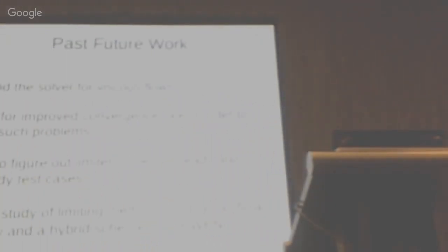So you're having an implicit solver. Yes, and then we also have the shock wave. Do we expect that we're going to have good convergence? Well, I would expect it should be improved regarding the split time scheme, but full convergence to machine zero is not a goal for this. That's why in one of the plots we try to track the CL evolution along the iterations to see if we get something like that.